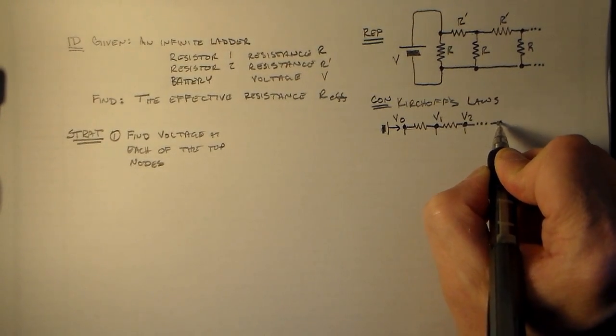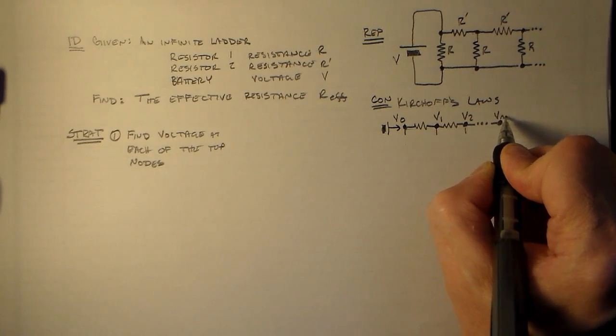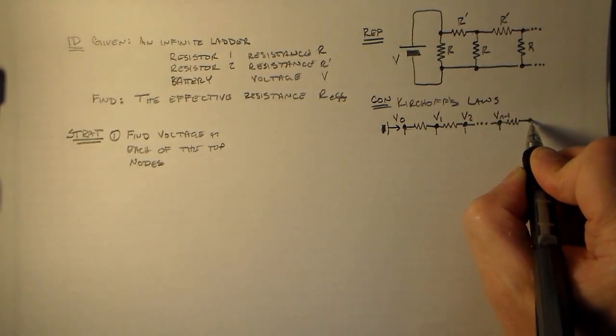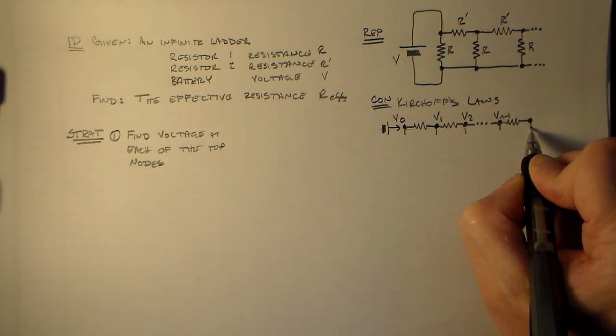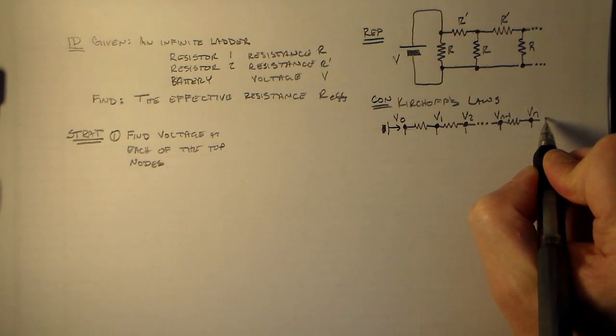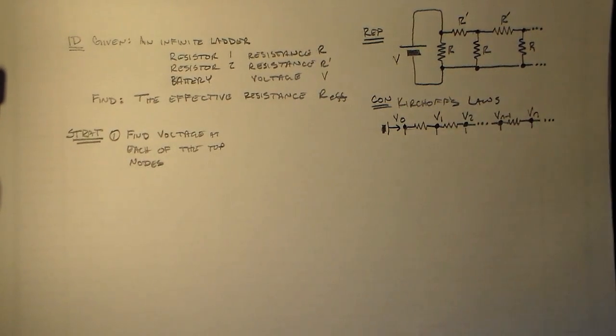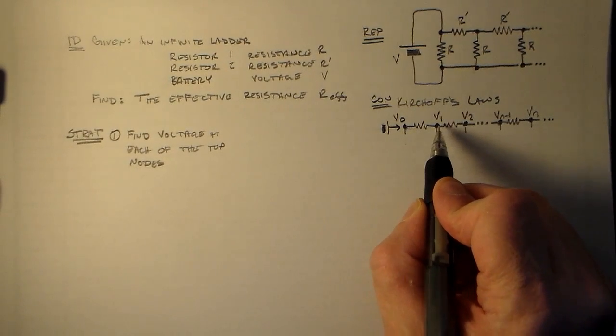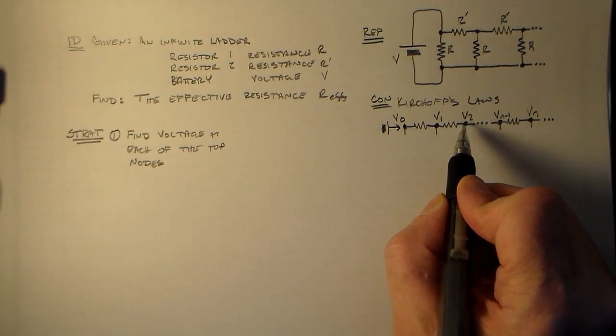and we've gone through n-1 of these resistors here, and then we go through this nth resistor, and then some of the current goes here, some of the current goes out, but this is the Vn, and then this keeps on going forever. All right, and whatever happens from here to here has to proportionately happen from here to here.